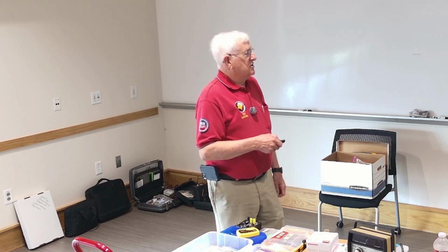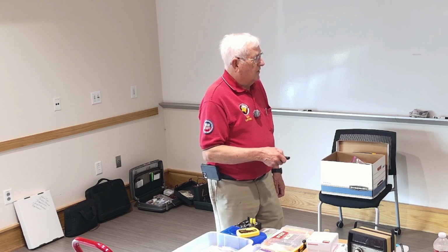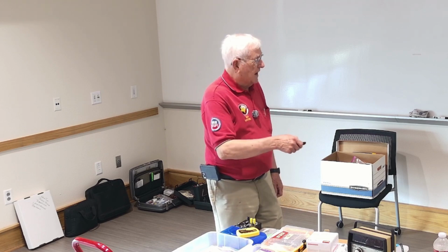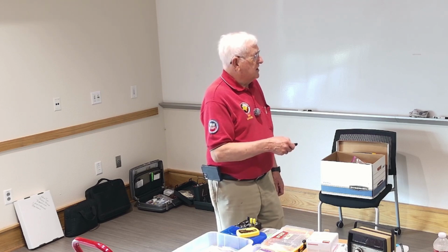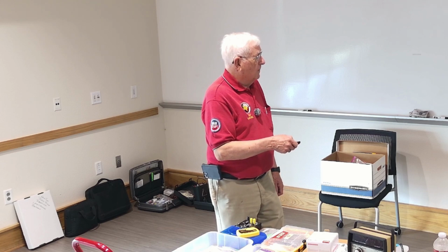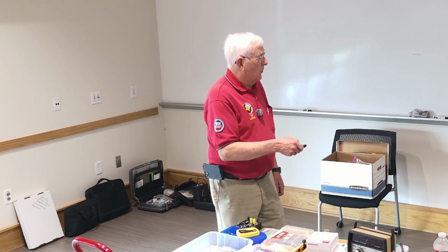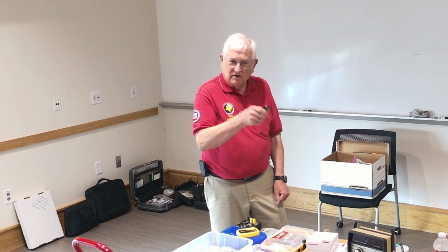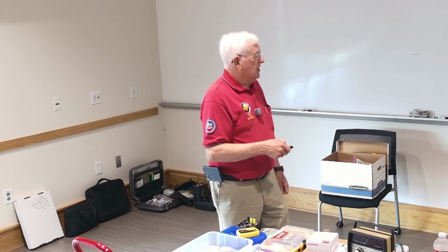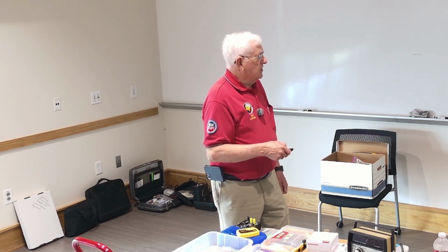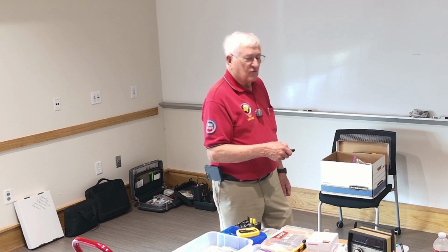The same thing then will be true with the horizontal adjustment. You can move this back and forth. So you move this, say, maybe to that point right there over here. And so you go from that point to get one full cycle of that wave on the screen to make it easy to measure. And then you would count 0.2 of a microsecond, 0.4, and so forth, whatever the time base is set for.